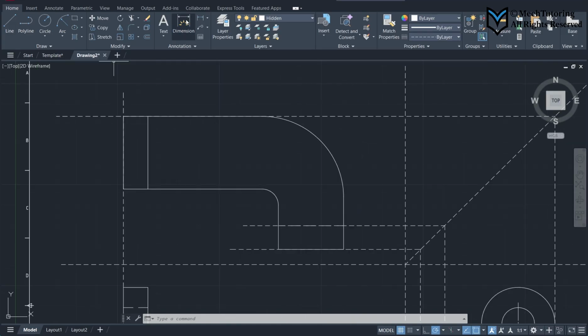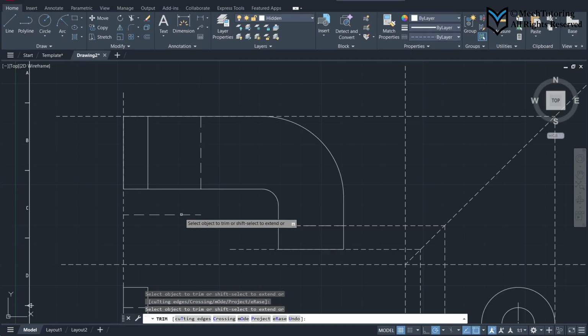Let's draw the slot. To draw the slot, let's use the construction line. Just hover over this line anywhere. Don't go over that corner. Just hover over this line and go this way by 1.9 and then go up and hit that line, okay? And then trim this and this. And the middle of that line is where our slot starts, okay?